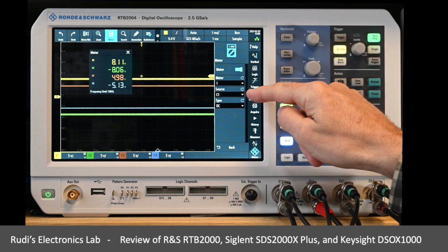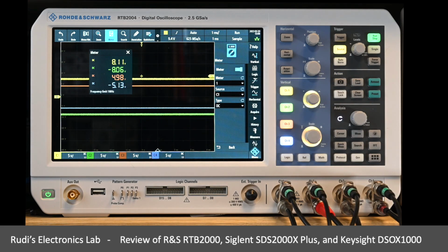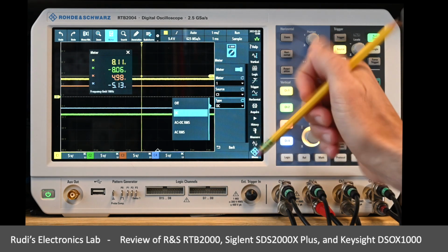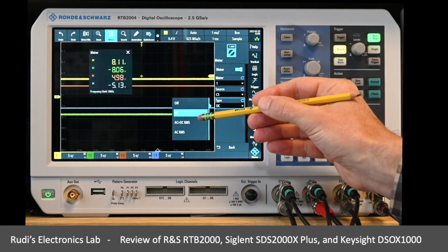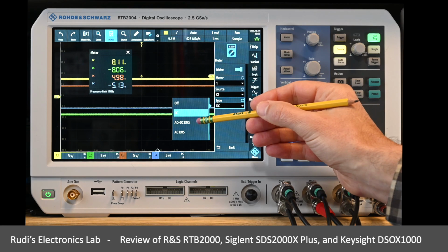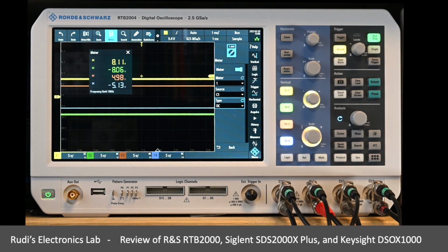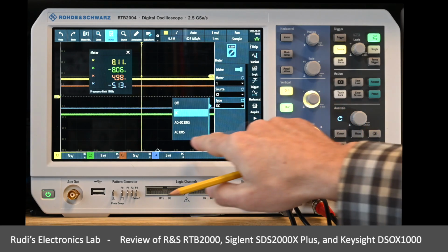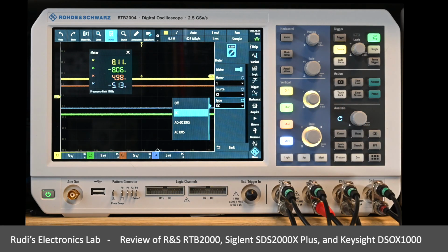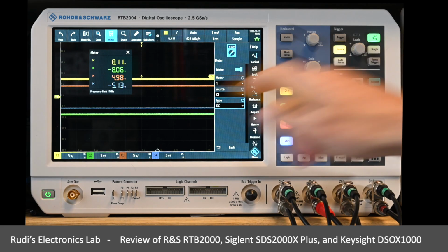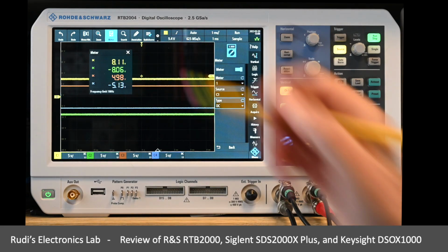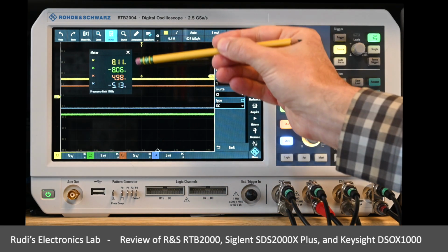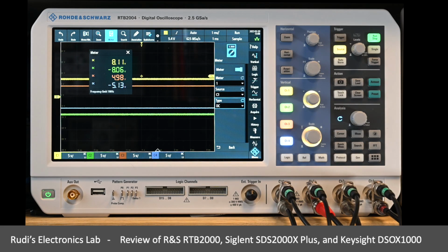So meter position number 1, source, and the colors here nicely correspond, like with most of the devices, with the channel that is selected. And I can choose here basically from direct current. I can make a root mean square RMS measurement, which includes both the AC and the DC component. And you can also take out the DC component and just look at the AC component. So you can do that for each of the different channels here. Now we see the DC component I've selected for all the different channels, and I see my 8 volt and my 5 volt power rails, negative and positive.